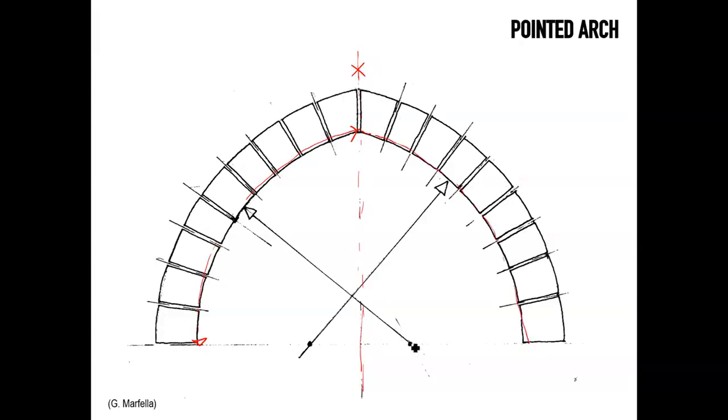They are both circular portions, but they are typically, like in this case, set up on center points that are about one third of the actual span. So you take the span of the arch divided by 3, and in the middle you might find two points that might be suitable for drawing a good pointed arch. That was often actually built in this way in Gothic architecture.